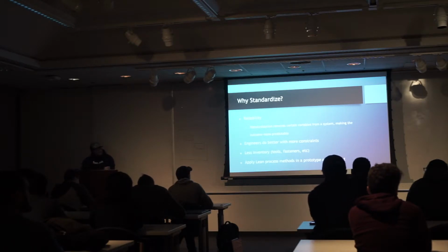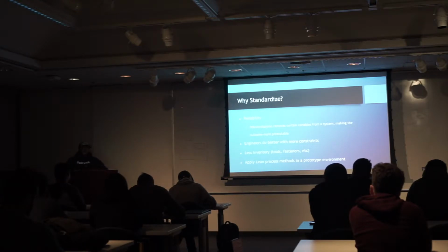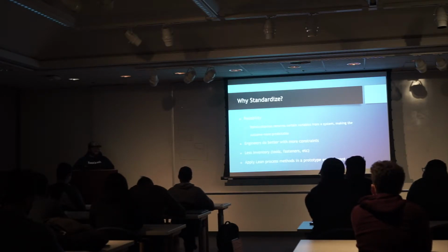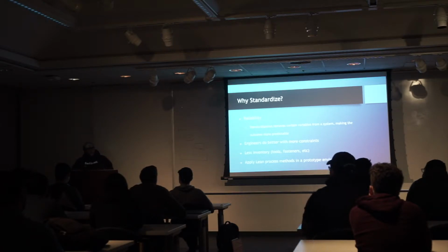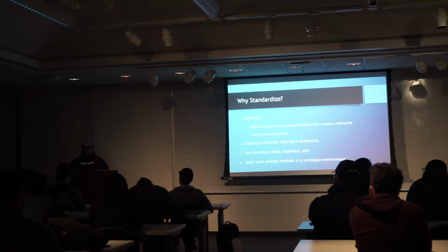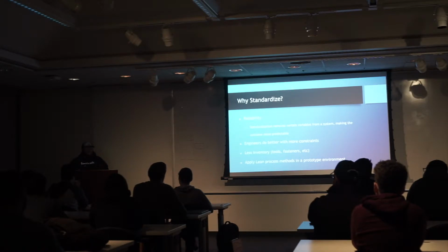One thing I'm curious about, not being super familiar with CNC stuff: are the things that you would standardize things like the rotor speed of the drill head, or moving across the surface or something like that? So we standardize most of our tools. There are different sizes, different drills, different cutting bits, different taps. We have a standardized list that are in the machine, measured and everything, and we do our best to use those. Those get roughly 90% of the work we need done. And then there's always going to be some weird special geometry that we have to build special tools for. But yeah, we standardize tools.